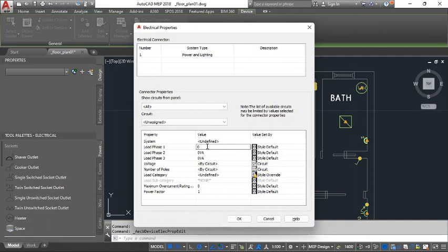And so this is for an electric range cooker. They're usually rated 1200 watts, or 1500, all the way to 2500. So we can give it a maximum of 2500 watts, which should be equivalent to, let's try the computation, 2500 divided by 230 volts.